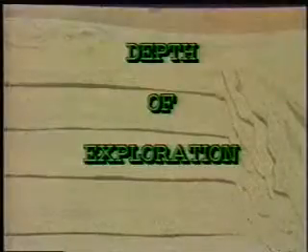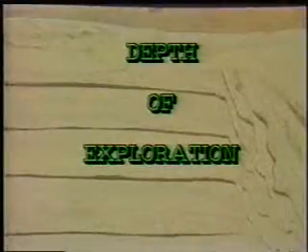The depth of exploration depends on the type of proposed structure, its size and weight, soil profile, and its physical properties. In general, the exploration should be carried to a depth which includes all strata likely to undergo undesirable settlement or shear failure due to structural loading.